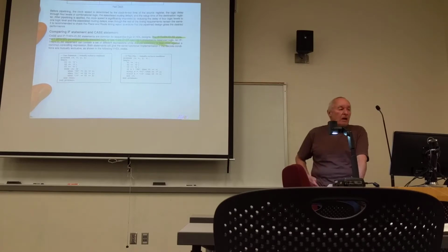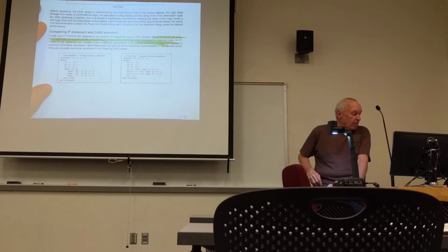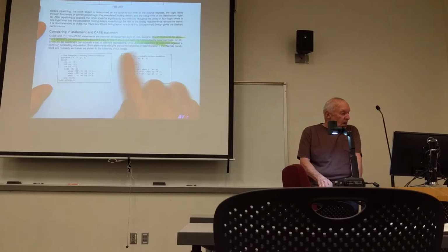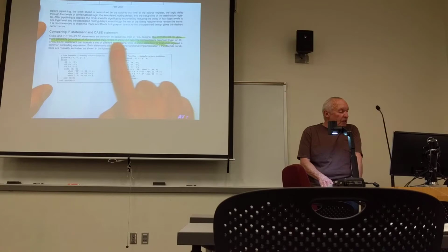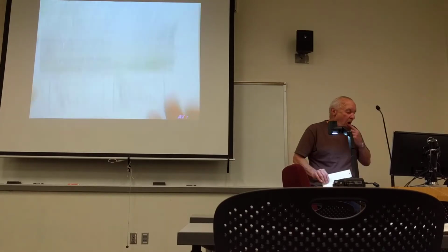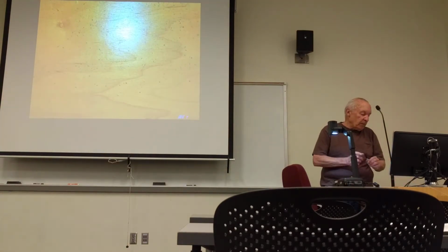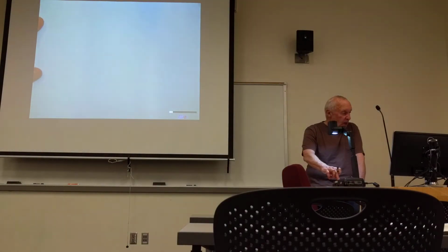Comparing if, then, else, and case statements. The if, then, else statement generates priority encoded logic, whereas the case statement implements balanced logic. Let me show you what they mean by priority encoded logic.